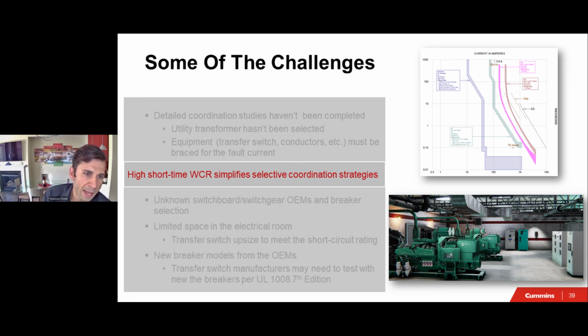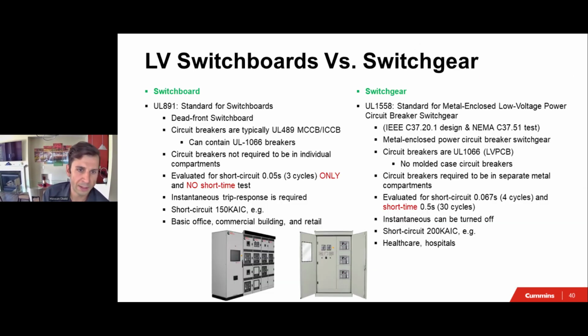Okay, so let's tie this back into the distribution board and switchgear quickly. A switchboard is built and designed to UL891 dead front switchboard. It only has MCCBs and ICCBs. There are no UL1066 breakers.